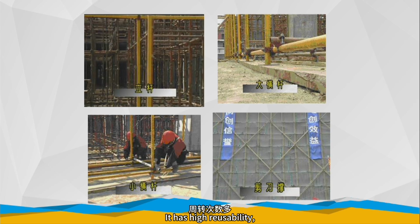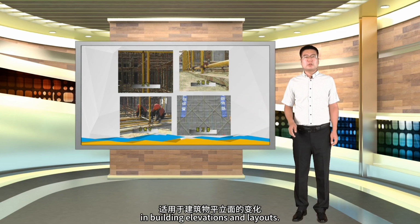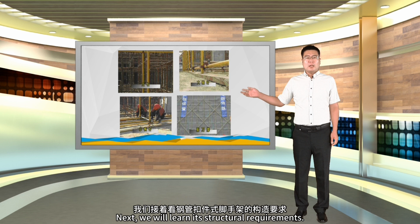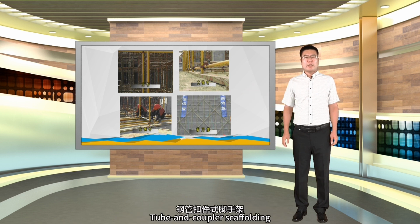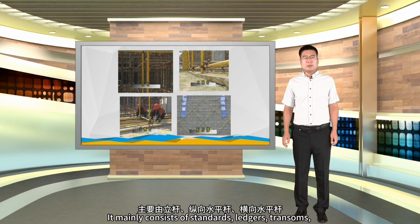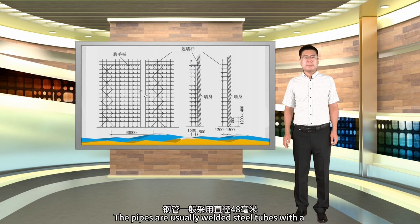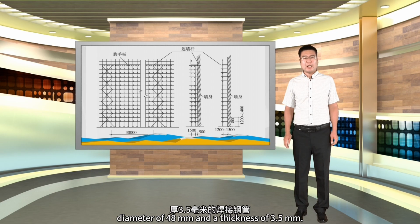It has high reusability, low amortized cost, easy assembly and dismantling, and good adaptability to changes in building elevations and layouts. Next, we will learn its structural requirements. Tube and coupler scaffolding mainly consists of steel tubes and couplers. It mainly consists of standards, ledgers, transoms, braces, planks, and base plates. The pipes are usually welded steel tubes with a diameter of 48 mm and a thickness of 3.5 mm.